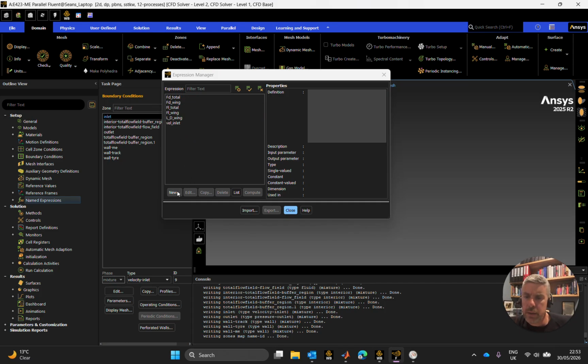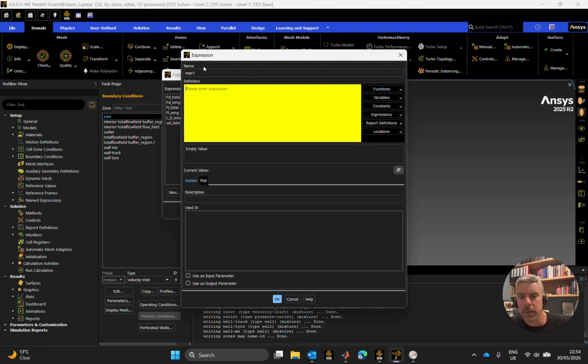Right, what else do I need to know? I also want to know the angular velocity of the tire. So what else? I'll need to put in the wheel diameter for that. Now, this is one of the cases where I've already specified what the wheel diameter was out of the geometry. So I have to write wheel diameter in here as well. I'm going to use that as an input, I believe, and then I can assign the input in the design table to be equal to what that input was out of geometry. So maybe stay with me for this.